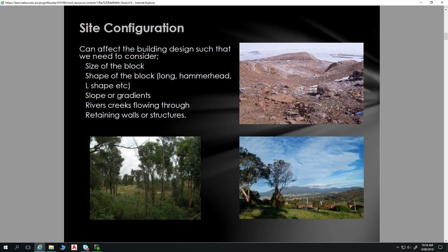So important things to understand, and we've got significant floodplain areas north of the city. So from Virginia out to Angle Vale, Two Wells area, a lot of that is floodplain, where you're required to pick a house up by 400 millimetres off the ground. Can be done with things like waffle pod slabs and so on, and we'll cover that later on.